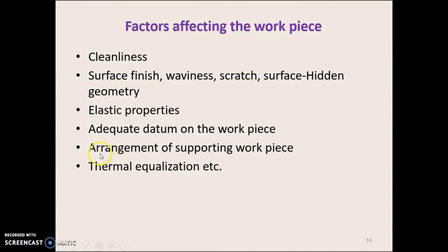Okay. And next is the arrangement of supporting workpiece. If the workpiece is of very small size and it cannot be held by the instrument, then we are going to have supporting objects for the workpieces. Whether those supporting objects are of correct cleanliness and correct surface finish, whether they are going to put scratches on the surface of the workpiece or not. All these things are to be considered.